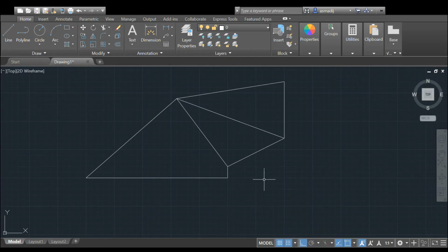All right. The next one is ortho. When you click ortho, whenever you draw a line, the line will be fixed to 90 degrees. So this is also useful if you want to create a boxy object. Okay, so ortho is useful, especially if you're doing orthographic drawings.